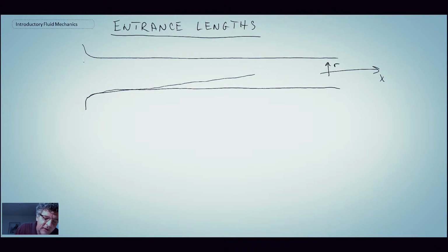And so coming in, quite often we show the realization of a top hat velocity profile, although it won't look exactly like that because we have this bell mouth here. But that's kind of an idealization that we quite often approximate in fluid mechanics. And then along the wall, we have the zero slip condition. And so the presence of viscosity diffuses out away from the wall, giving us a velocity profile that goes from zero to some free stream amount, or the amount that we would be seeing at the inlet. And so that's what the velocity profile would look like.